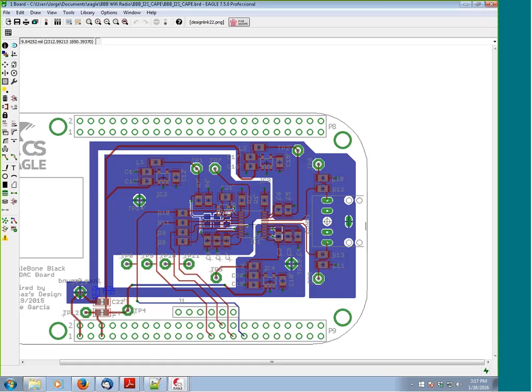I understand if I were doing an RF thing, that would not be okay under any circumstance. But for this situation, it was more vital for me to keep this circuit close, and the way these sections ended up working out put that power supply over here. But it was okay because it's very low power, and this part right here is just power rails.